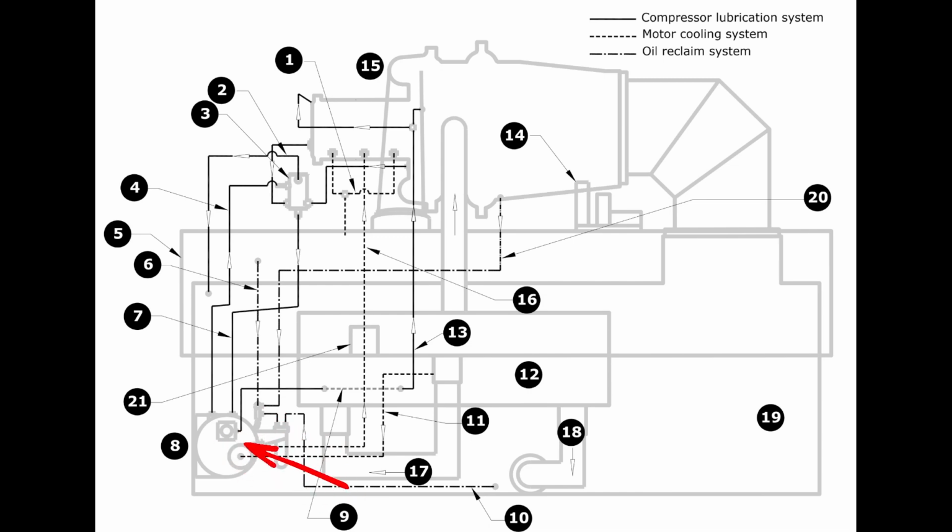We don't want liquid refrigerant getting in here, or, if it's like that Dunham Bush as an example, we start to send liquid into our compressor. That's what the oil line returns to, the suction line right next to the compressor, so it doesn't have far to go. So the point is, we need to be careful with these valves, that we're tuning them properly, and that we're not opening them too far.